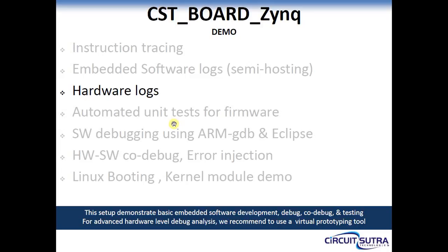By setting different values of log level in the config file, the user may activate different kinds of logs or information messages being printed. We are setting a log level of 3 for the UART model.